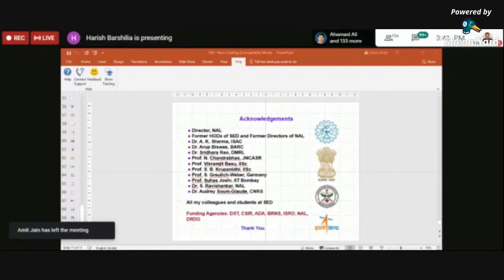You take a titanium Ti6Al4V plate and keep it in the plasma chamber, and after 2-3 hours, once the diffusion layer is formed, you will find that corrosion resistance, hardness and wear resistance are always there in that kind of system. The second way is that you can apply some sort of coating, for example a titanium nitride coating if your temperature is not very high. It depends upon what kind of application you are looking for. If you have a particular application, I can recommend a specific coating.